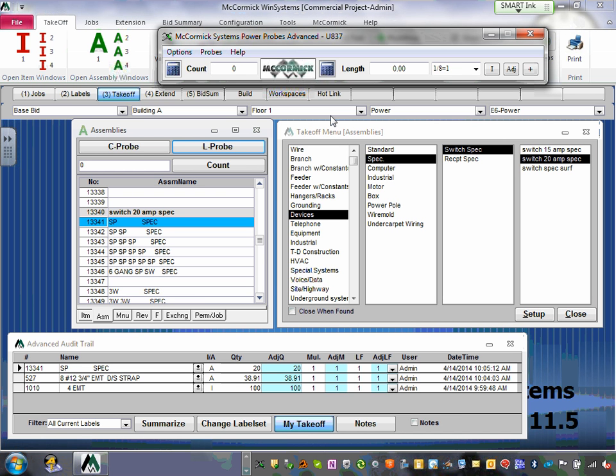You move them through the conduit. So every time you cross from one side of the wall to another through a door, you have to go up. Well, let's make this a 12-foot ceiling. When you go up, go 12, and when you go down to a receptacle, go 12. How about if we go 12? That will include some slack.